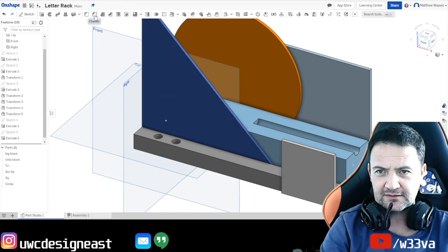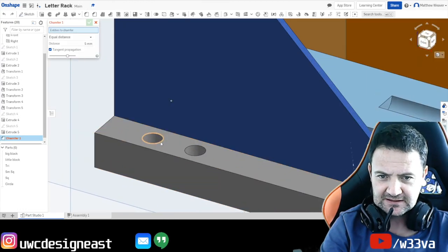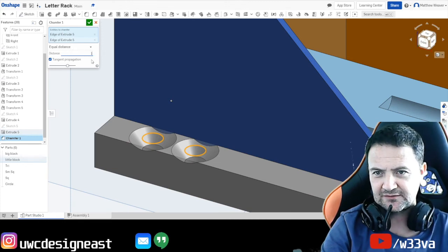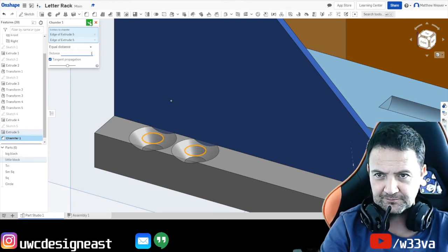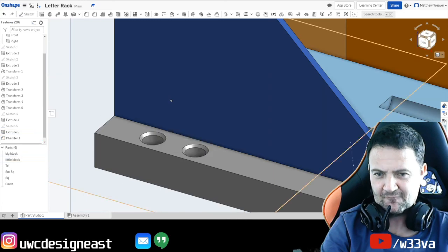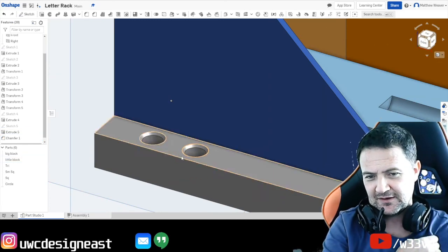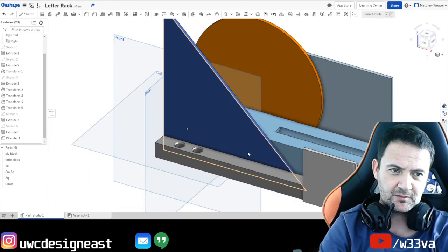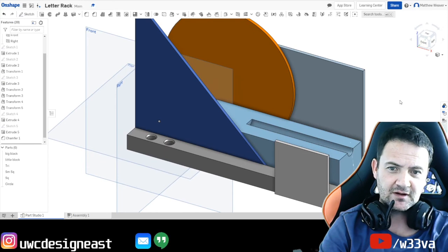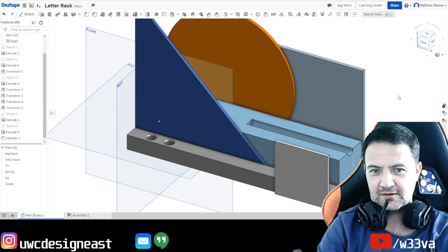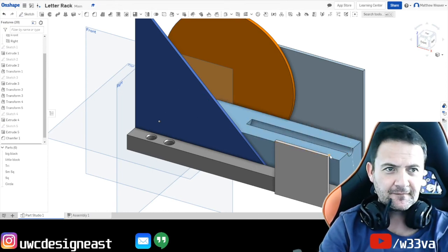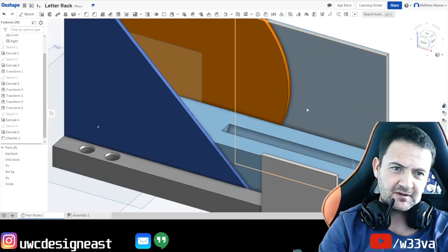We'll do one more thing so you can see. It's called a chamfer. Okay, so if I click chamfer there, and click that side, and that side, and go to, let's do 1. So, okay, can you see that little opening? And that's just going to help me put my pencil in there. And of course, you can do that with something we call a countersink, or you can use a larger drill, or you can wrap your finger up with a bit of glass paper and start sanding that out. Okay, so that's pretty much it.